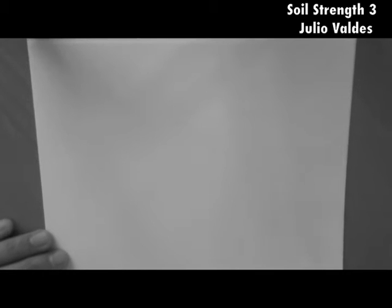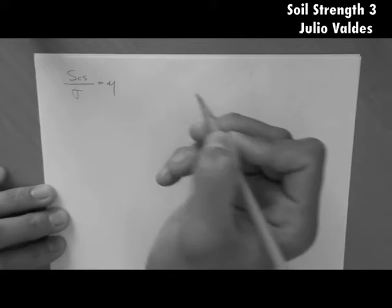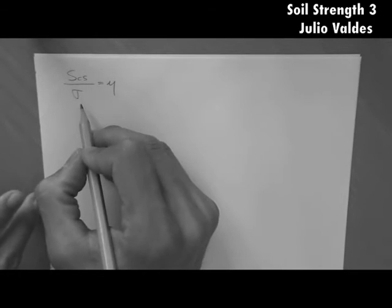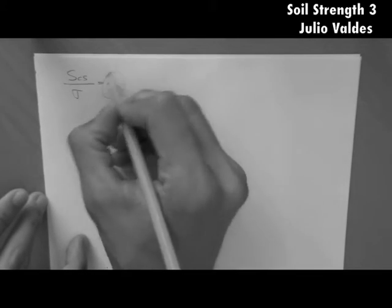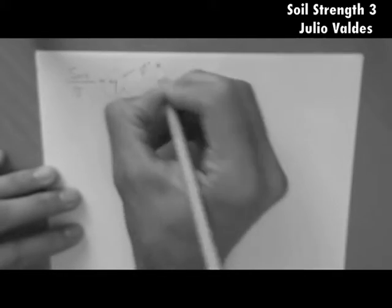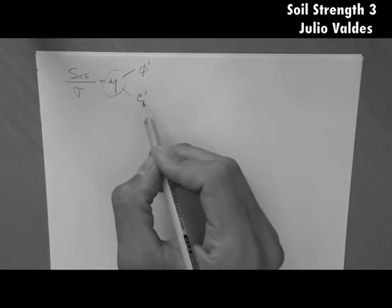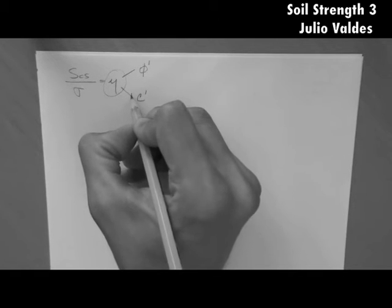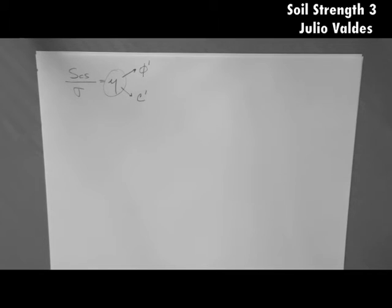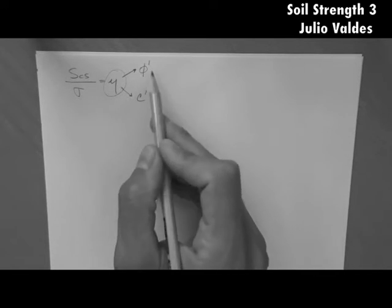Let me just turn this around. All right, so this is the equation we know so far. We're not going to use this equation particularly. We're going to expand it and you'll see why. This is actually, let's say, separated into two parameters. One is called phi, the other one is called C prime. The mu is actually more related to the phi prime rather than the C prime. But basically what I want to show you here is that for soil, the relationship is not mu. The relationship is described by two parameters. Okay, you'll see how this comes about.